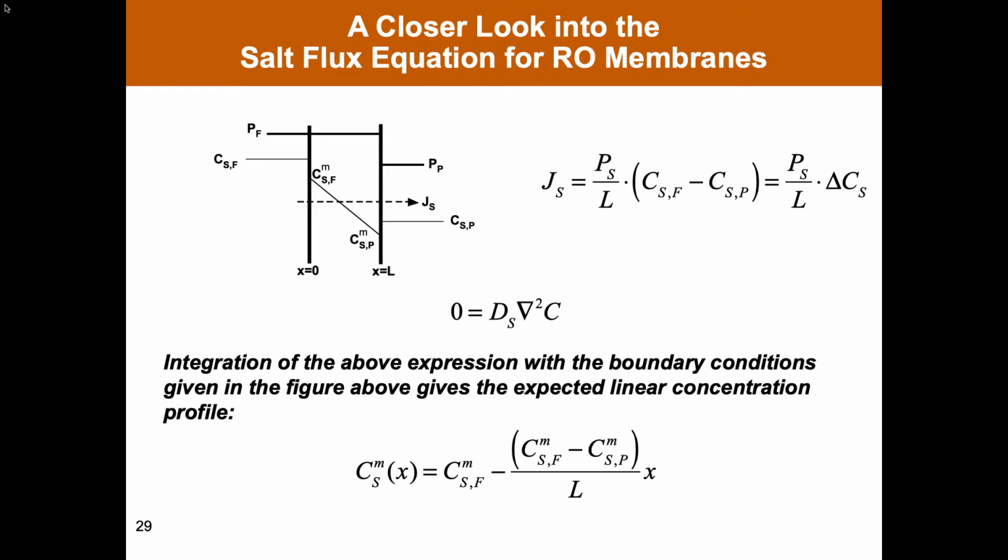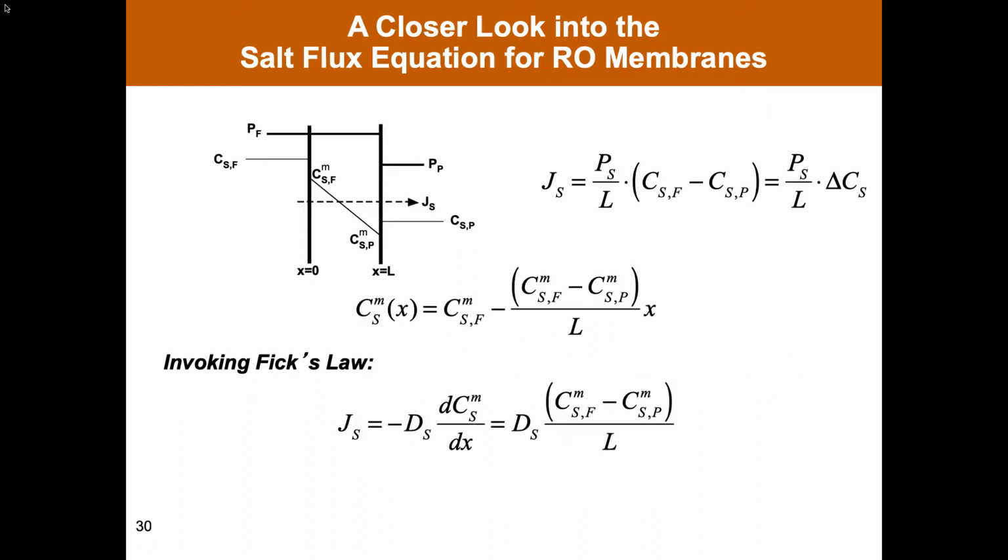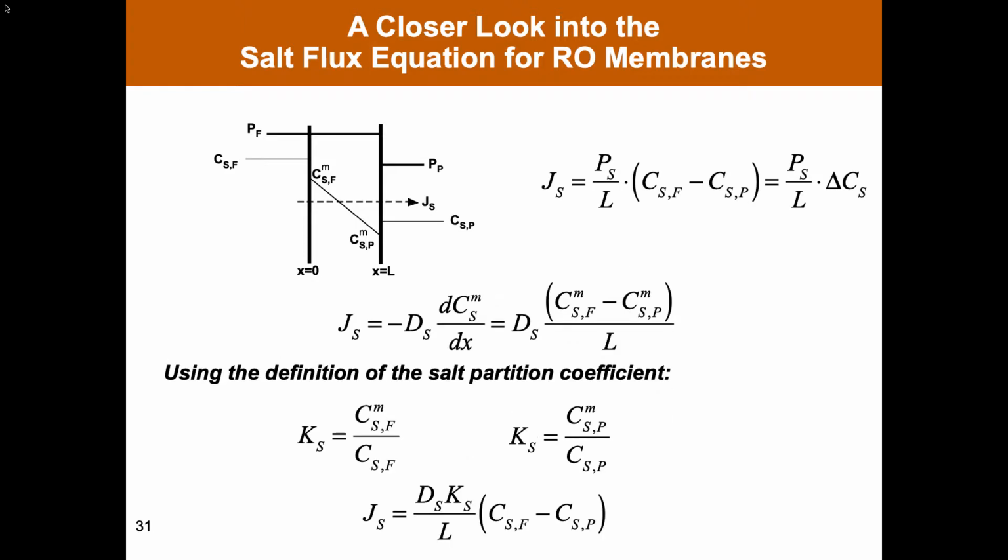And so from this expression, we can integrate it to give the concentration gradient across the membrane, and we can put that into Fick's law with constant diffusion coefficient, and get the relationship between the salt flux and the concentration difference inside the membrane. It is typical then to connect these internal concentrations to the external concentrations using a partition coefficient.